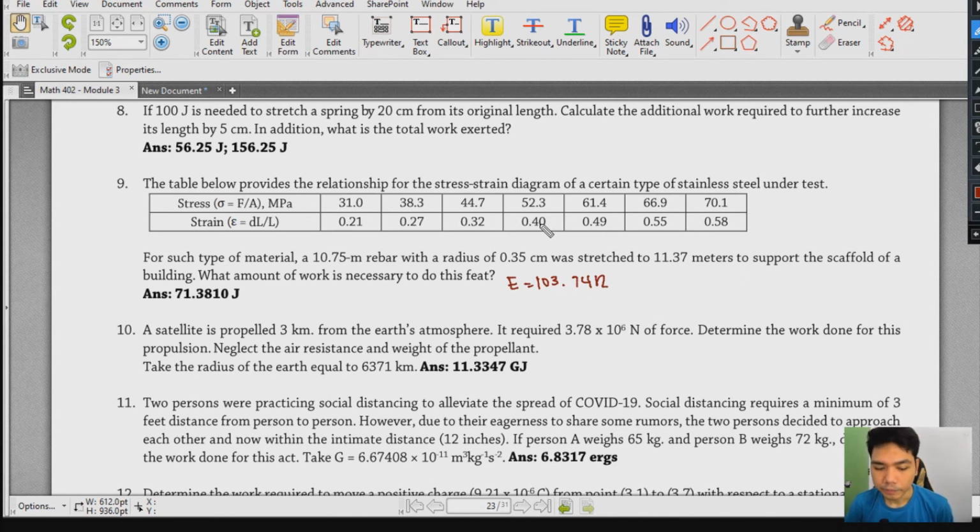So what is that for? We need that in order to generate the equation that we'll be using in terms of Hooke's law and the Young's modulus. There is one equation that is very vital in this process. Remember, the elongation or the compression or the displacement could be represented by this delta symbol, the Greek letter, and that is equal to F multiplied by the original length divided by the area and the Young's modulus of elasticity.